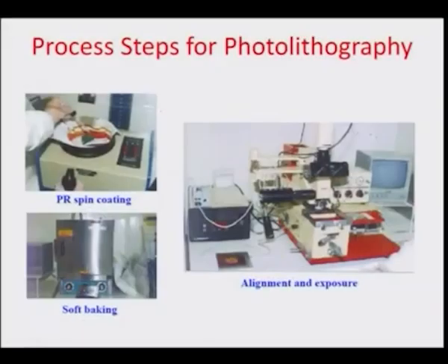Okay. So, this for example is the spin coating of the polymer resist. As I mentioned, photolithography has a very important process step of coating a thin layer of resist material onto the wafer surface. This for example is actually the wafer surface, and you are applying the resist on the top, and this is a spin coater. So, it would spin at a certain controlled RPM, and you can spin thicknesses defined by spin speeds onto the top of this wafer. Once it is spin coated, you can heat and soft bake the resist, so that whatever liquid is available here for carrying the resin material is all evaporated and the resin is all set.